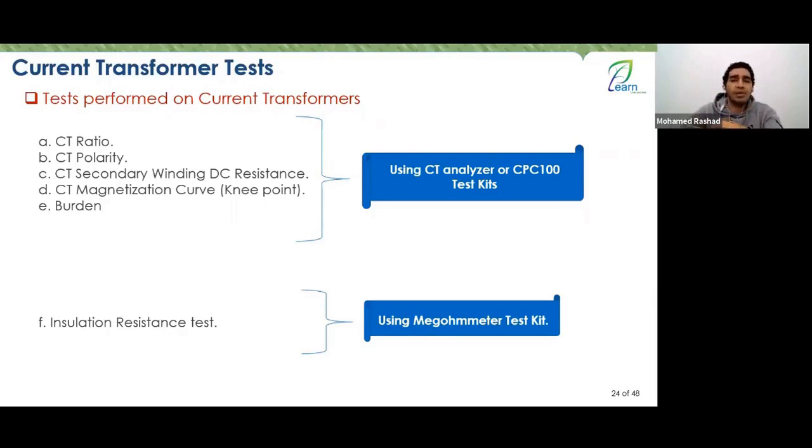Also, I'm talking about whether it's an ammeter, a power meter, or an energy meter. Here, the direction of the current will matter to me in terms of power direction, whether it is exported or imported. The same applies to reactive power; in the end, it also matters to me in terms of the power factor, whether it's lagging or leading and so on. Very nice. Okay, so that's regarding the directions in energy.